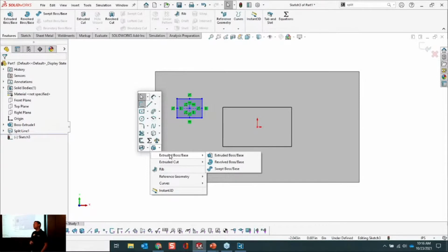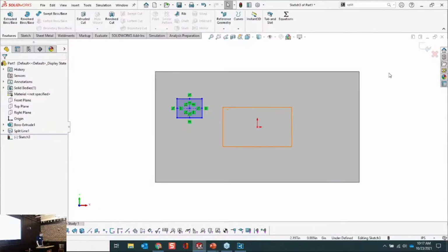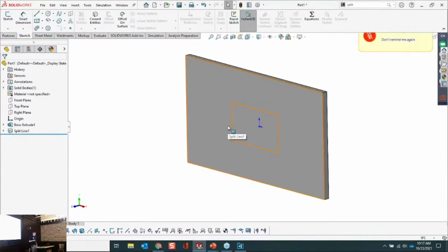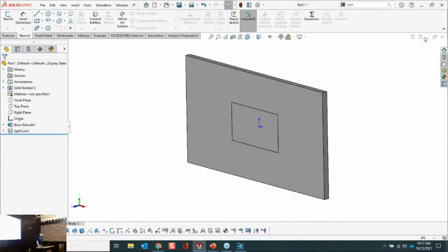If you already knew about the S key, maybe I'll tell you something about it you didn't know. This is 2021 that I'm using now. In 2022, it actually takes this search bar up here and puts it on the S key, physically on that mouse button, and then you can search for any command you want on top of the S key. So this is by far the quickest and most powerful shortcut that I could teach you. If you're not using this, break your habit, whatever you're doing today, and start implementing the S key into your day-to-day. It is definitely worth it.